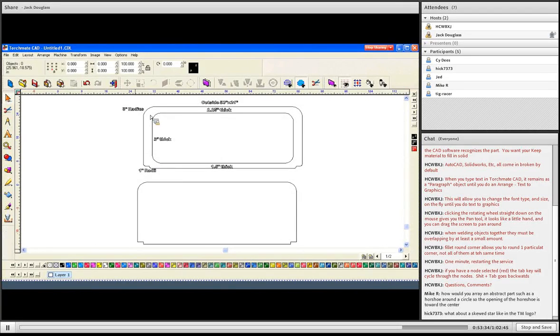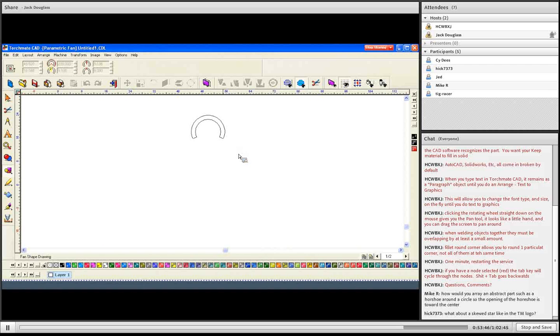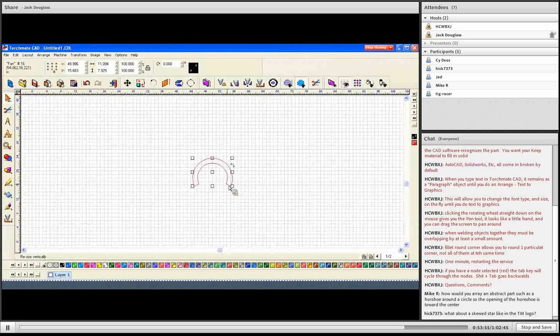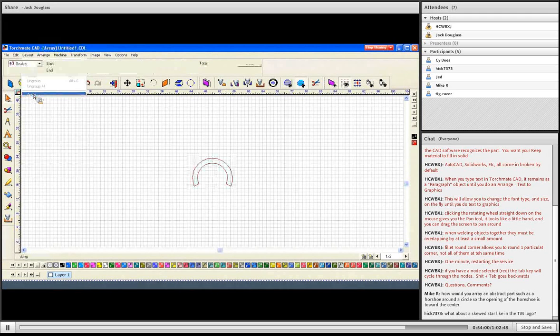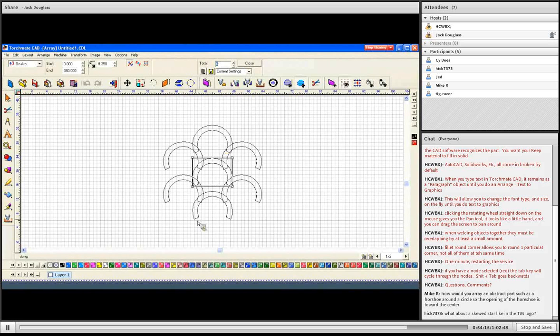So let me clear all this out here. We'll just start with the first part. We'll even make something that looks like a horseshoe. So say an object like this, if we wanted to array this, but always have this opening part facing the center, go up to Layout and Array. Now on arc, just to spread them out here, on arc will not rotate them. So as I duplicate them, they're all facing the same way.